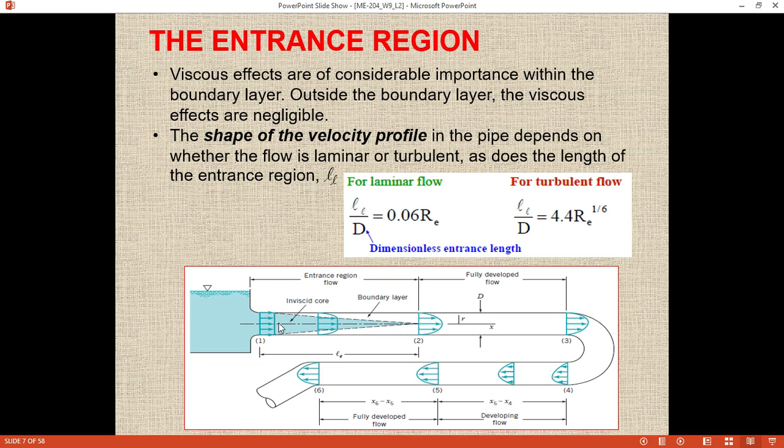So your wind tunnel must be designed in such a way that you can get an inviscid core long enough to bring your car within this core. And you should also know the width of the core.